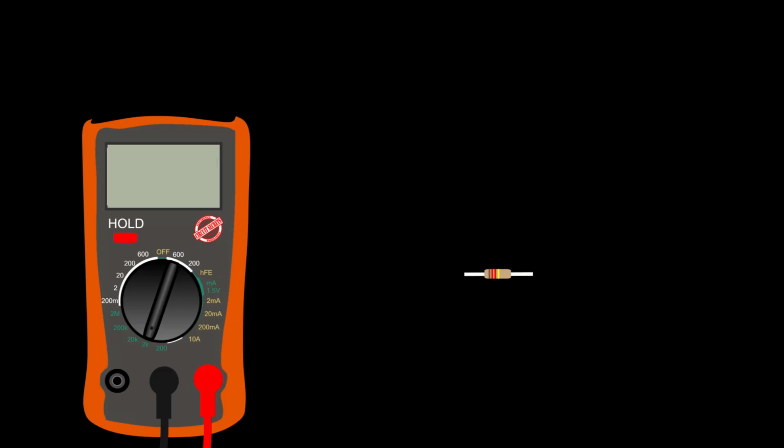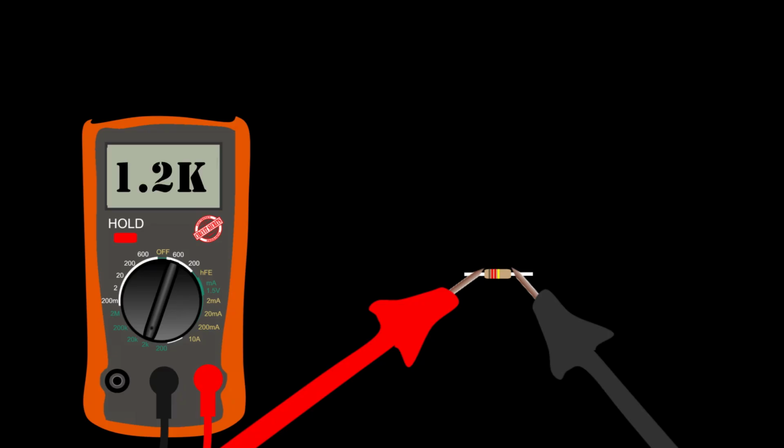Finally, there is the measurement of resistance. This measurement requires the circuit to be disconnected from power. It is best to measure individual resistors with a multimeter in the resistance or ohm setting and with the component disconnected from the circuit to prevent false or inaccurate readings. If you attempt to measure the resistance of a circuit with power passing through it, the meter may be damaged.